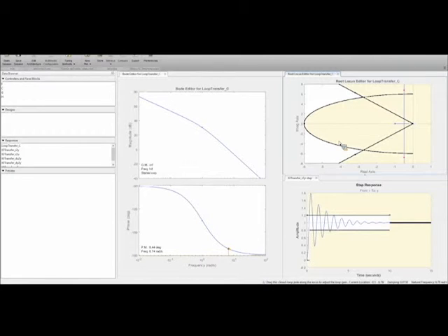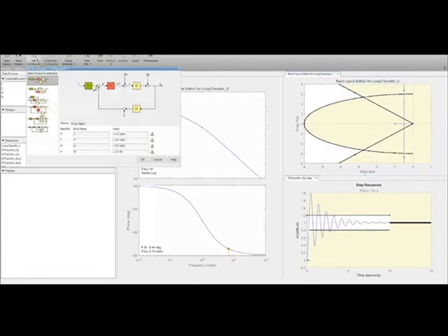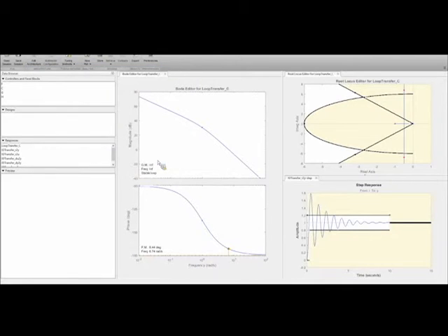We see that this is not going to work. So then we can add controllers, or a compensator to this. And so that is in this block C. So if you ever need to know what the architecture looks like, you just go to Edit Architecture, and it'll show you what all these labels mean if you forget what F, C, G, and H are. But C is the controller in terms of how MATLAB specifies it.